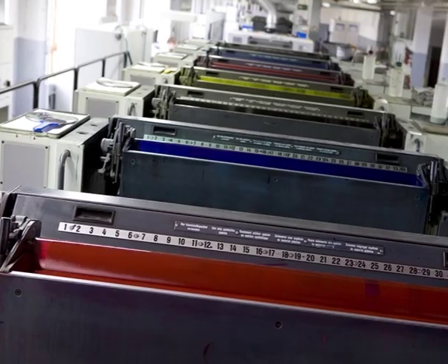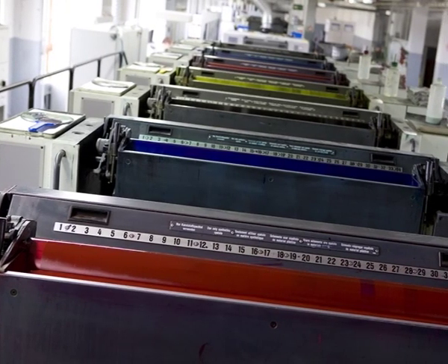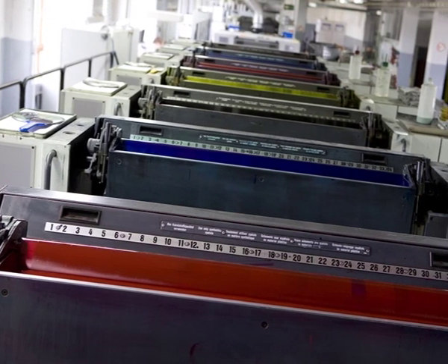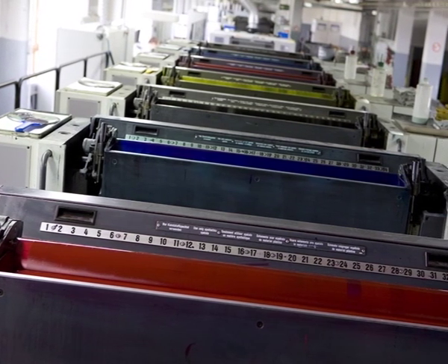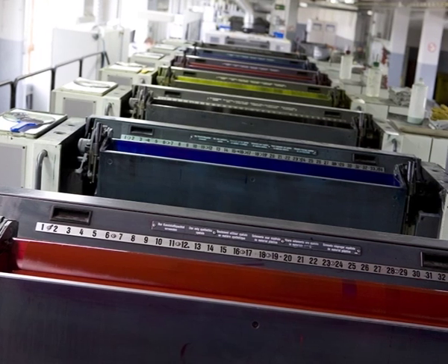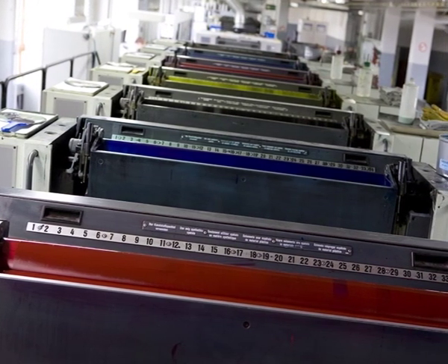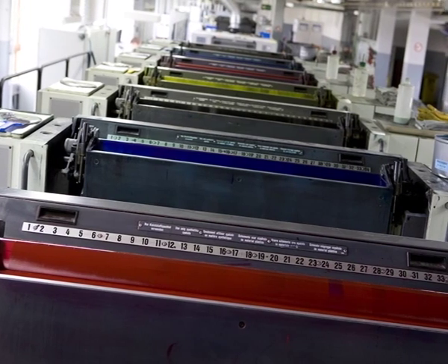It is essential that the paper surface does not pick when printed, as pick means that some of the deposited ink may be lost from the surface, and in extreme cases the paper surface may start dusting. This means that the size and binding agents are not working and the fines of the fillers and opacifiers are loose on the paper surface.